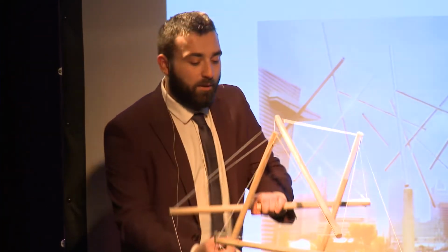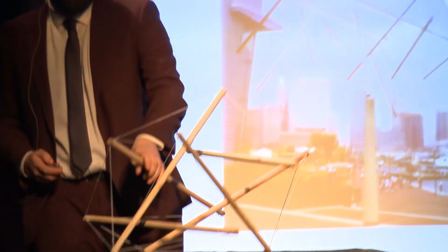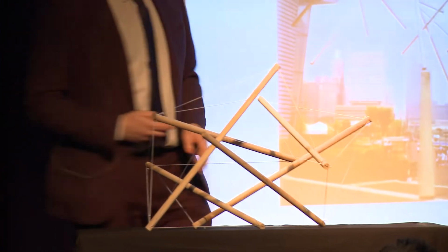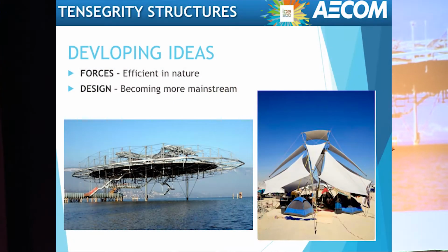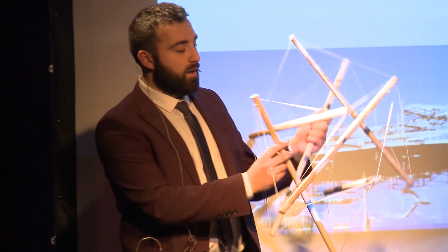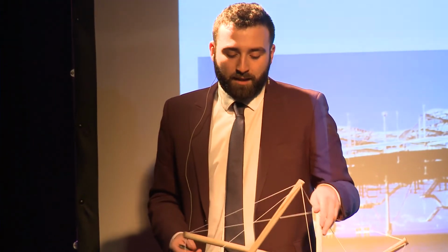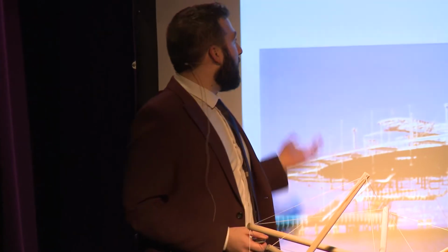Initially, that was only used in the likes of architectural art installations and sculptures, like the ones we see here, and even my one. However, when you look into tensegrity more and look at the design loads in it, if you apply a load somewhere in the structure, it gets impacted somewhere else. So if I squeeze it here, you can actually feel the load in the back strings. What that means is tensegrity can be used as an efficient way of design. It's new and modern, and it's becoming more mainstream due to the way it dissipates forces throughout it.